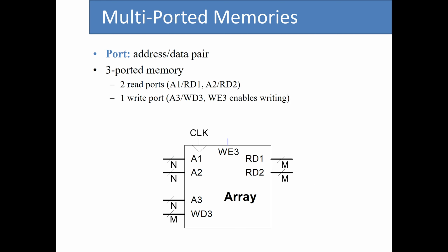So in addition to the regular memory arrays that I talked about, we can have multi-ported memory arrays. So this is useful when you have, let's say, you want to work with larger array sizes, right? Or you want to have several read ports and, let's say, several write ports. So this is an example of a multi-ported memory array. So we have 3 ports. We have 2 read ports.